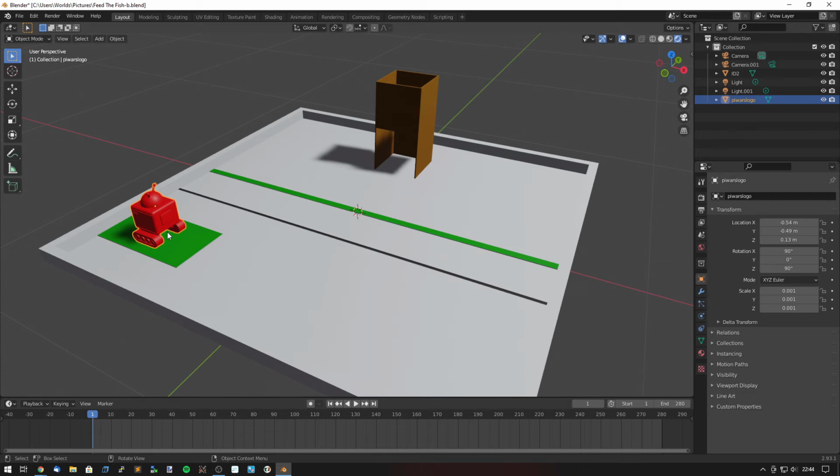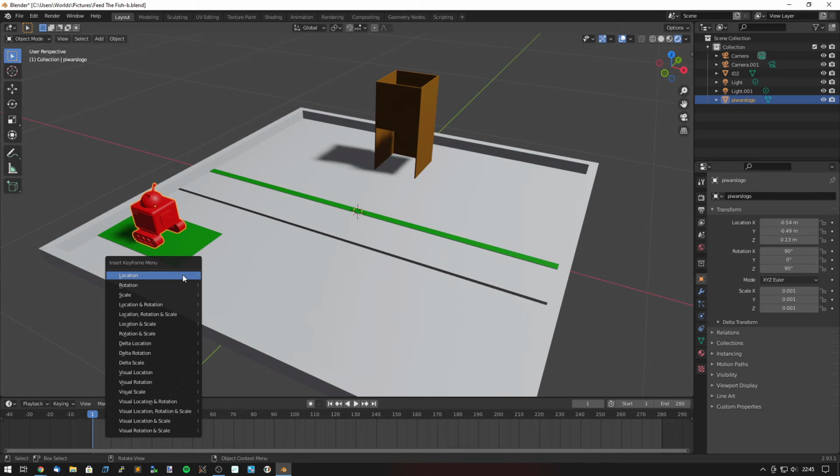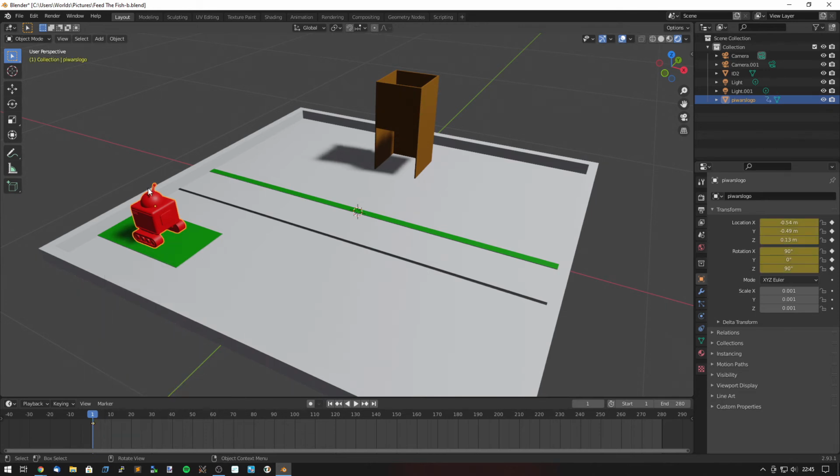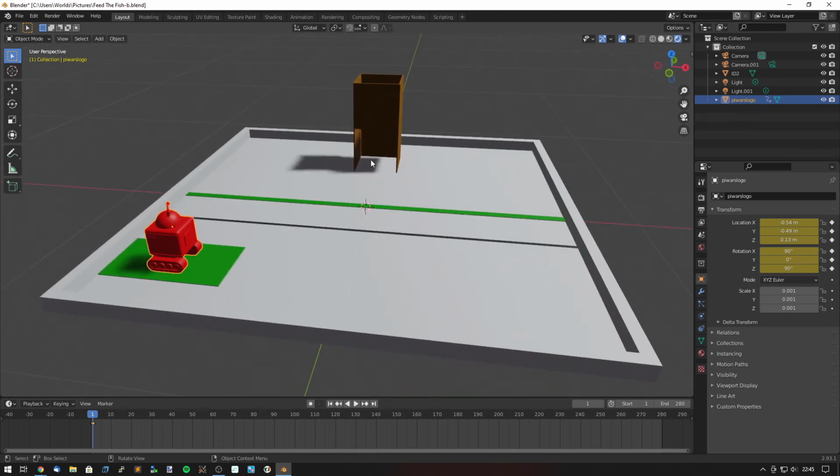So basically you're going to create a keyframe initially by pressing the I button, and that will ask us what type of keyframe. Now this is where we want to say, I want to lock, in this case probably, the rotation and location. Say yes, it's location and rotation, that's the object I'm selecting, that's where it needs to be at that marker. So this is very important that you keep that blue line where you need it to be. So I'm going to say after 1 second, I want the robot to be in front of this. So basically I want to move it to here.